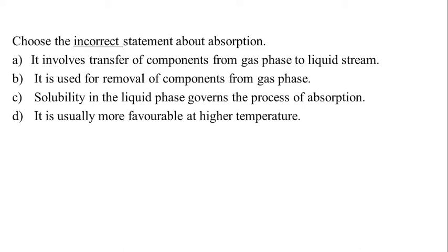In case you have a reaction, in many cases, a very strong reaction, your equilibrium line may not remain linear. But in most other cases, in case of absorption, usually a linearity of the equilibrium line is taken, and the computation becomes much easier, and basically you can do the calculations using the absorption factor, which is a very common thing to do.